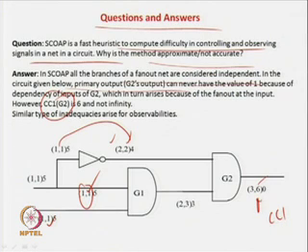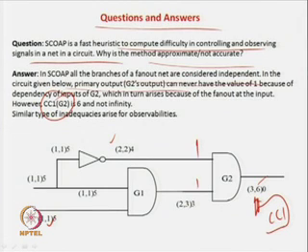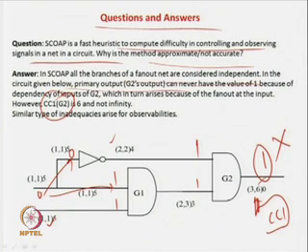But now we will see, it is very interesting, that you can never get a 1 over here. It is saying that the combinational controllability of this being 1 is 6. That means you have to apply a 1, 1 to get a 1, correct? Now to get a 1 and a 1 over here, you have to get a 1 and a 1 over here. To get a 1 over here is an inverter, so you have to get a 0 over here. So, to get a 0 over here, you have to get a 0 over here. So, this is 1 and this is a conflict. So, you can never get a 1 over here. So, the difficulty to get a 1 over here is not 6, it is infinity.